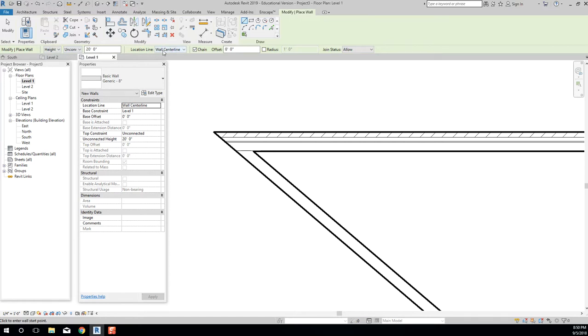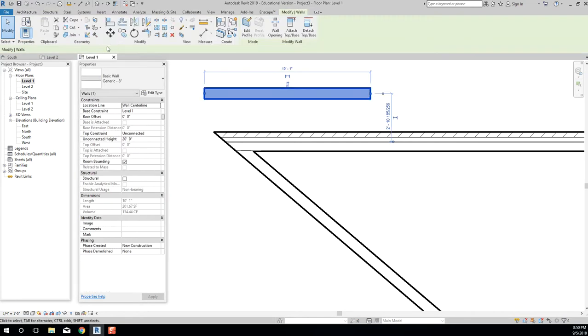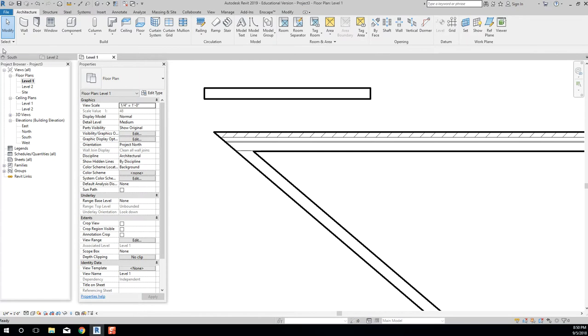This is a perfect instance: all of these different settings for my wall show up in the modify toolbar only as I generate a wall, and they don't show up again in that place. If I draw a wall now, press escape, and click on it, those options are gone, although a lot of them do show up in the properties dialog box. So as you create things, this is where the modify toolbar will be located, and a lot of settings can be defined in that modify toolbar.